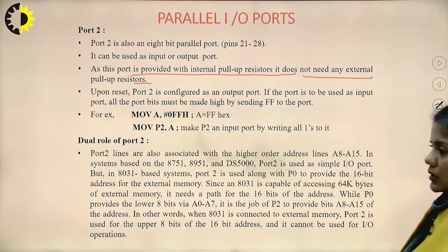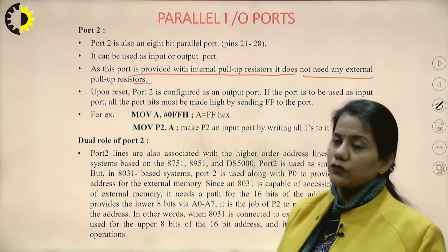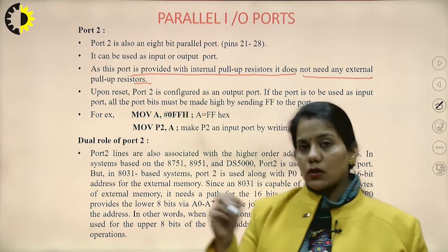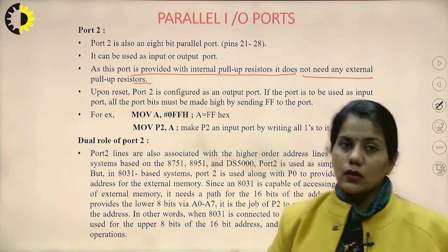Upon reset, it is again configured as the output port, and to make it as an input port, again we have to send 1 to all the pins or to the corresponding pin which we want to make as the input pin.